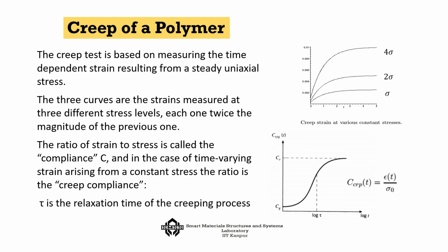Now, similar to the creep of metal, we are talking about creep of a polymer. What are the important things? First of all, the creep diagram is not like primary and secondary; it is continuously changing all along. And as the stress increases, it becomes more and more prominent with respect to stress, and you can draw it very nicely like this. If you say this is the primary part, even the secondary part is not stable, and then the tertiary part till the rupture.